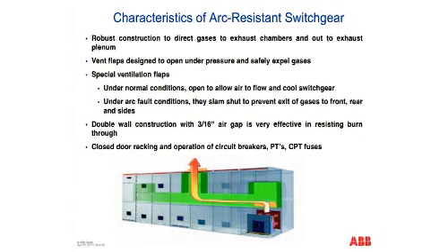One of the elements that folks need to recognize about arc-resistant switchgear is that it is designed differently than regular switchgear. When you start laying out a typical switchgear, you're just worrying about stacking breakers and making sure your bus size is right. In arc-res construction, there are a number of issues that need to be addressed. Number one is that I have to have vents. Every X number of frames, I've got to have a way to get those gases up to the plenum. And depending upon whether I have 3,000 amp or 2,000 amp breakers in it, the number of those vents that go northward will increase.